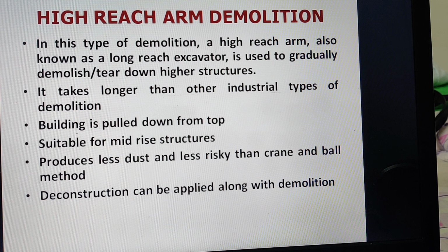Let us talk about high reach arm demolition. In this type of demolition, a high reach arm, also known as a long reach excavator, is used to demolish or tear down structures. It takes longer than other industrial types of demolition. The building is pulled down from top to bottom, suitable for mid-rise structures. It produces less dust compared to implosion and is less risky than the crane and ball method.